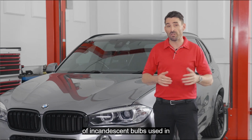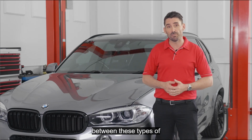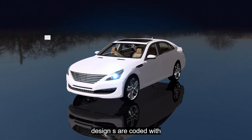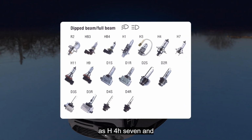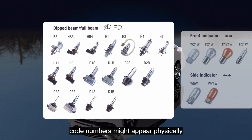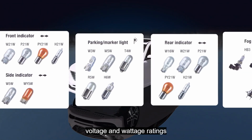There are several types of incandescent bulbs used in today's vehicles. The differences between these types of bulbs lie in the base design. Bulbs are coded with numbers for replacement purposes, such as H4, H7, and the like. Bulbs with different code numbers might appear physically similar, but can have different voltage and wattage ratings.